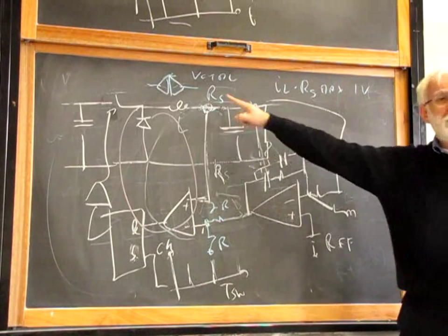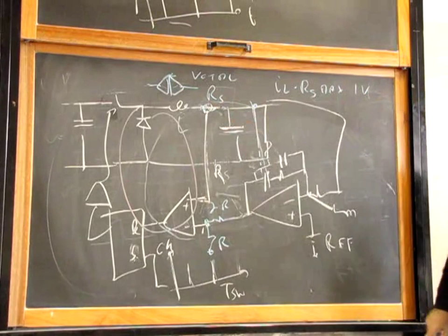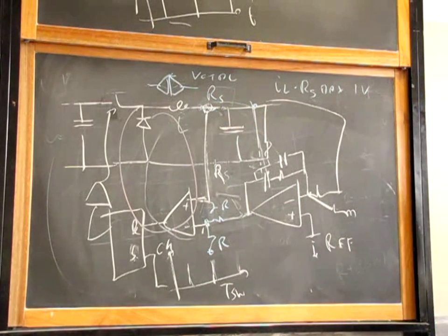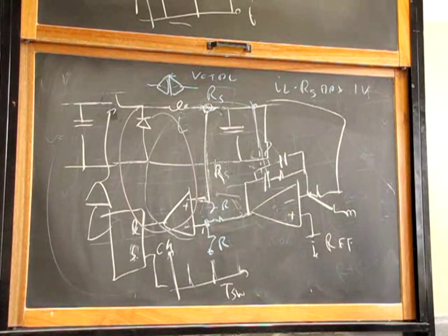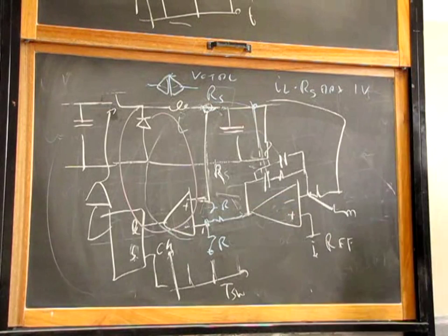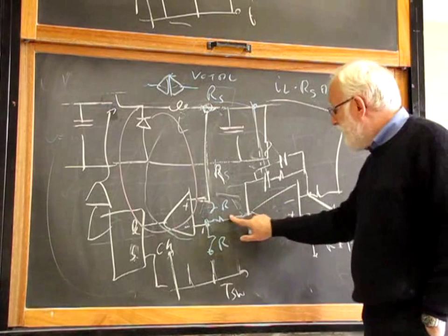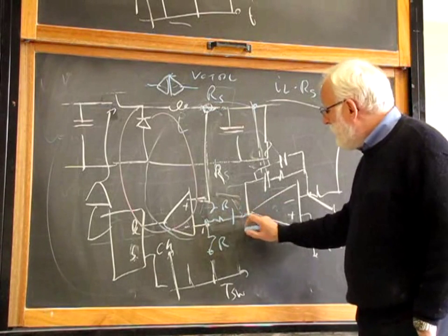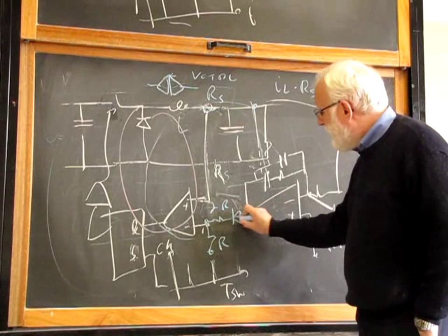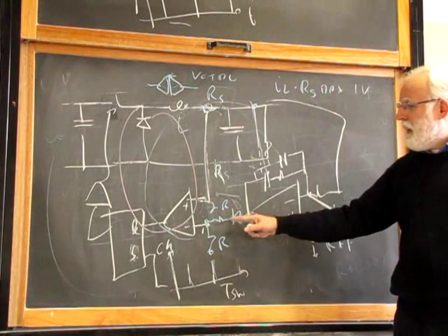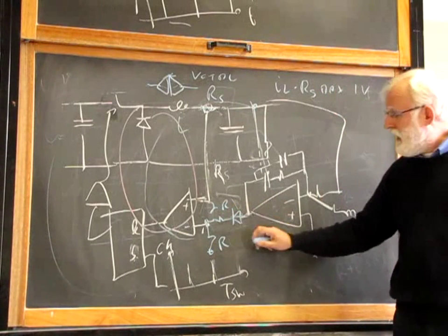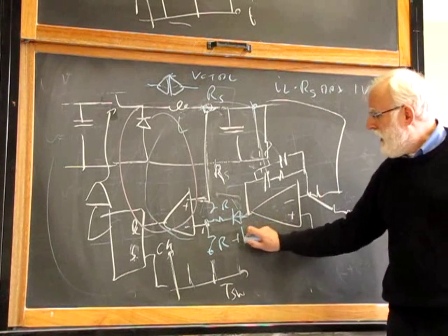So this is happy and this is happy. There is still one problem, and the one problem is that this amplifier cannot go down to 0. It has a minimum headroom voltage on the negative side. And so in some cases they put here a sort of a diode, basically they do something more sophisticated, in order to have a voltage drop here. It's like placing a battery like this.